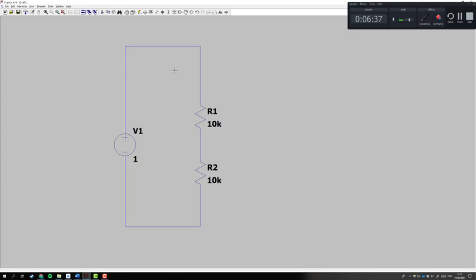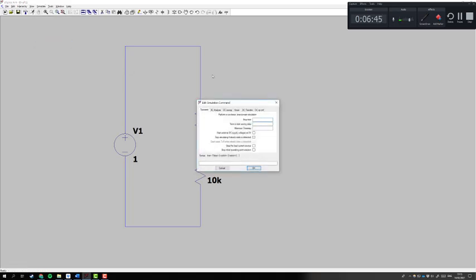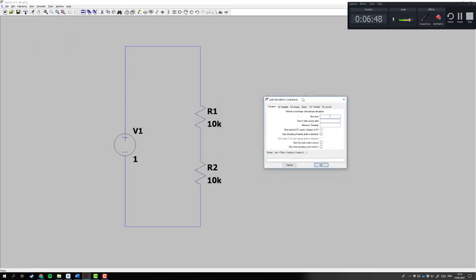Now, there are a couple of types of simulations that we can run. So let's look at the simulation tool, and we're going to click on the Edit Simulation command. This is where we can edit our simulations, and we've got a few choices. We've got transient, so just look at what's happening to the circuit passively in time. We've got AC analysis: if this is a frequency source, what happens to a particular value as the frequency increases. And then the other one is a DC sweep: what happens to an output voltage as you sweep an input voltage?